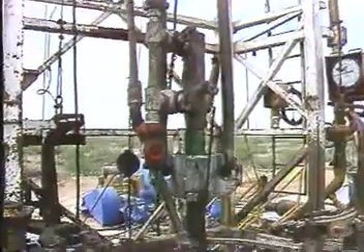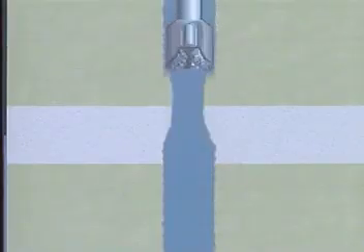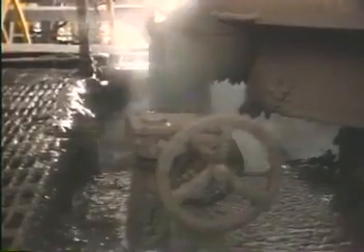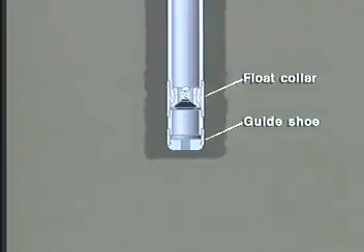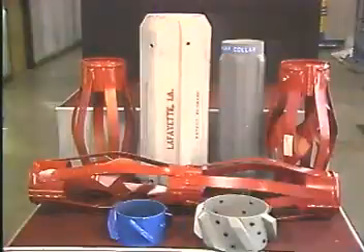A good cementing procedure will also provide the following directions. First, condition the hole by reaming out tight spots. Condition the mud to remove cuttings and maintain a low viscosity. Install a guide shoe and float collar to prevent overdisplacement. Where appropriate, install scratchers to remove mud cake from permeable zones and install centralizers at appropriate intervals.